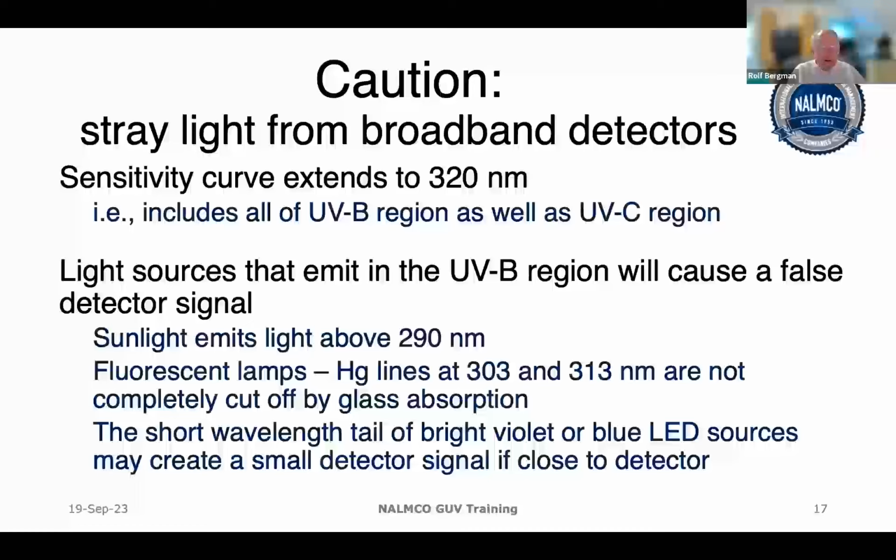that there's no reading on the detector with zero offset. If there is zero offset, then you can correct it by setting the offset to be the continuous wave background. It'll subtract whatever reading you have. I didn't mention that LEDs, if they're quite bright at 450, even have a tail that we can see with the gigahertz meters. So even LEDs have to be carefully accounted for.